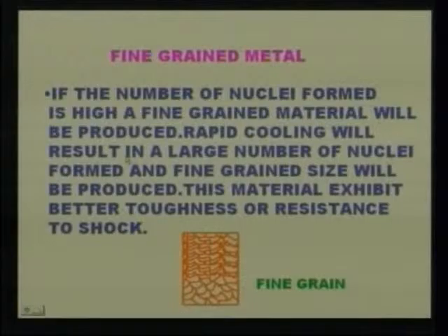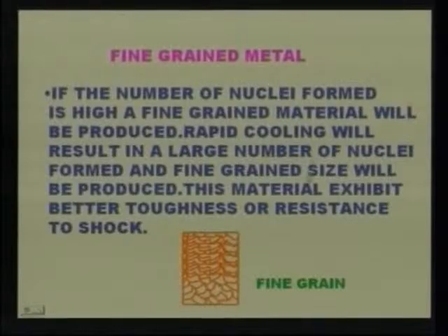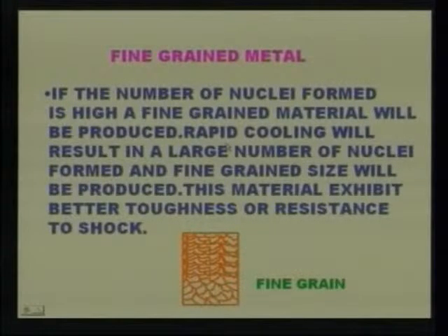Rapid cooling will result in a large number of nuclei formed and fine grained size will be produced. This material exhibits better toughness or resistance to shock. It also increases yield strength, tensile strength, etc. These mechanical properties are increased. This fine grained material will provide more advantageous mechanical properties, whereas coarse grained material is not that advantageous to